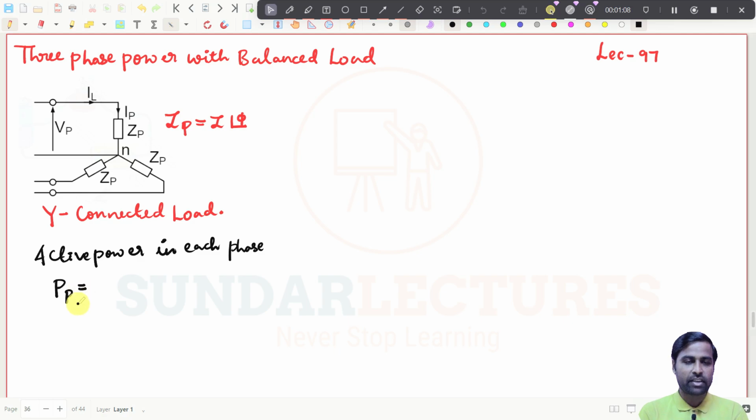P per phase will be equal to the voltage across these two points, that is VP. This is not the line voltage; I have told you that is the line voltage, but this is the phase voltage between neutral and a single point. It will be VP into IP into power factor, since this is an AC circuit. Obviously you will get a power factor, as we have seen in single phase AC. So this is the per phase power if the load is star connected.